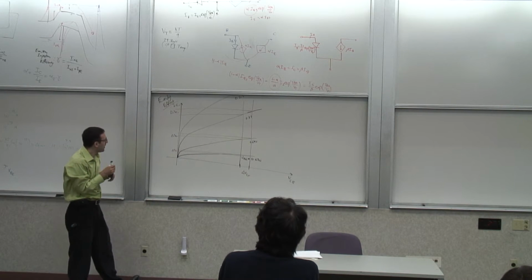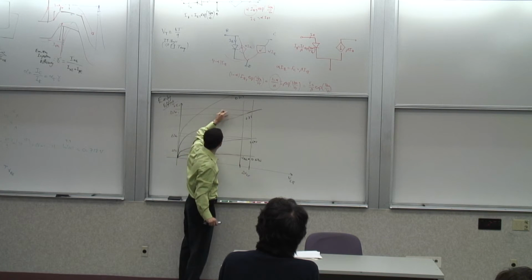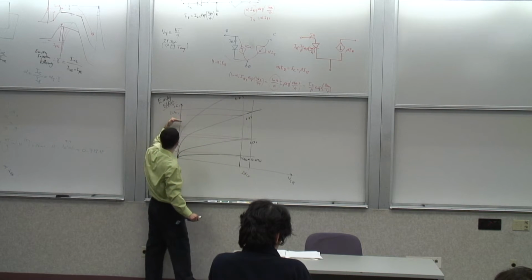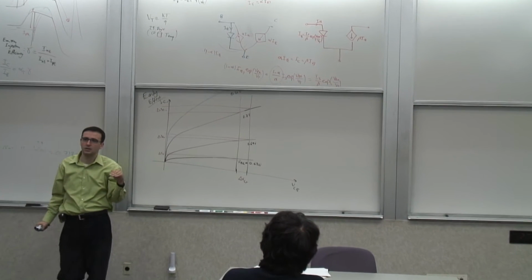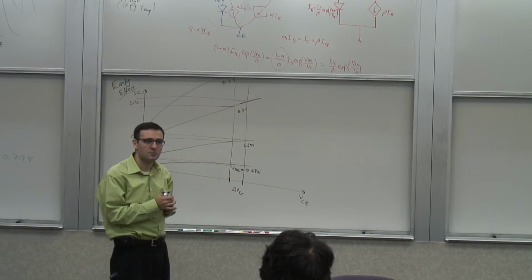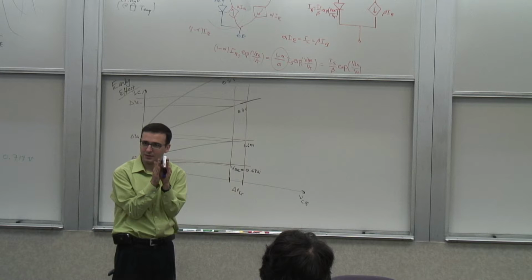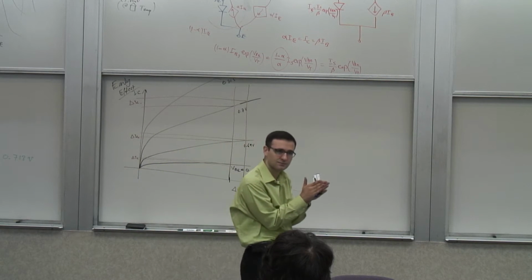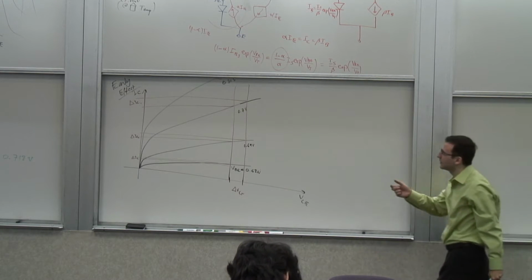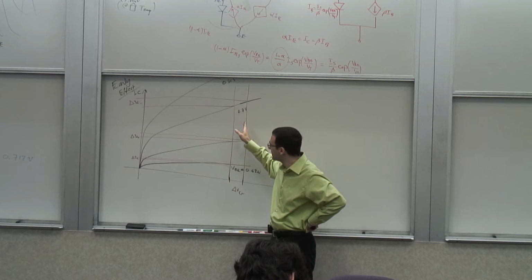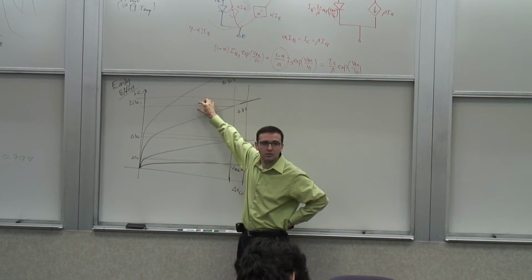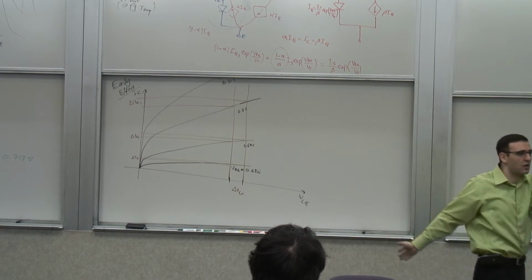Right. Now, is it expected to see this change in the current that's proportional to the absolute current? You see that for larger DC currents, for larger ICs, my delta IC is larger too. Is that logical? Yes. Why? Because when you decrease the width of the base, you increase the chance of electrons passing, right? So the fraction of electrons that can pass is changed. But for a given fractional chance increase, the larger the current, the larger net number of additional electrons that will pass, right? So if 10% more can pass, 10% of a larger number is a larger number than 10% of a small number.